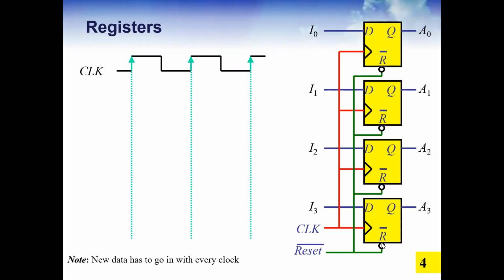And we know the characteristic of the flip-flop: whatever is connected to the input, the state will not change until we trigger the flip-flop, meaning until we give the clock. Whatever the input is, let it be. The stored value will not change. States will not change unless you trigger it.